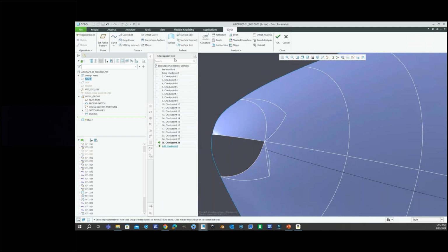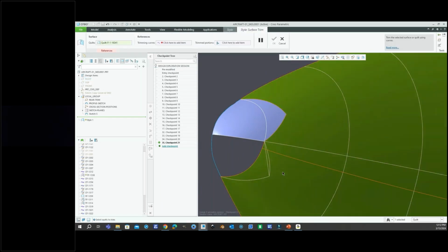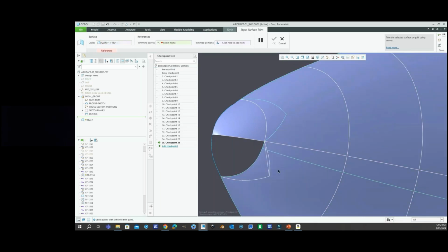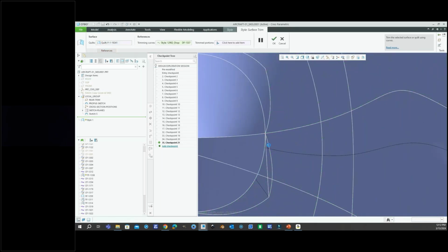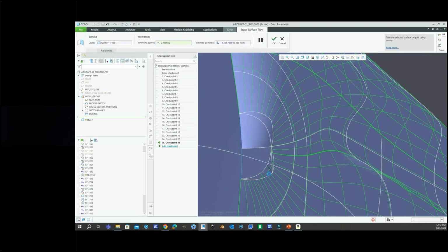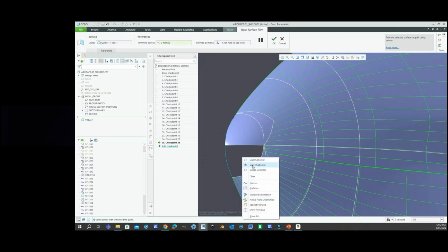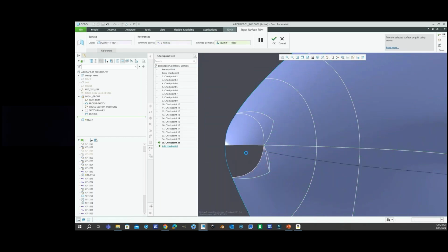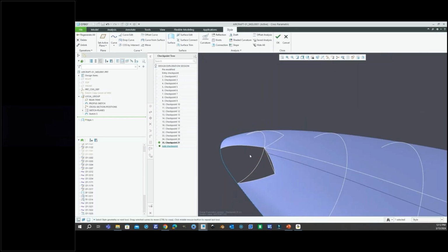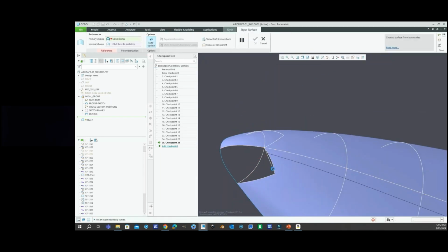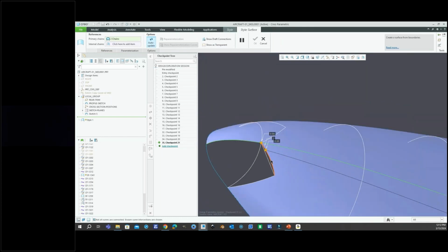And then same thing, I can just go back in here and trim this out. So there's a surface to trim. There's my curve collector, and I'll select these curves here. And then I'll choose the surfaces to remove. Okay, so now I have that 4 boundary again, which will allow me to go back in here and I'm going to hold shift to get that second boundary chain, then control the third and the last one here.